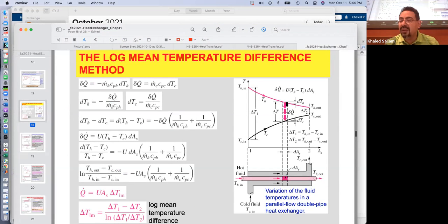It's not like the hot is always transferring to the cold in the next step. In cross flow, the cold kind of goes and leaves and comes again, exchanging heat with one part of the hot fluid and then coming back and exchanging heat with another part of the hot fluid, just because of the way they're trying to pack a lot of surface in a tiny place.